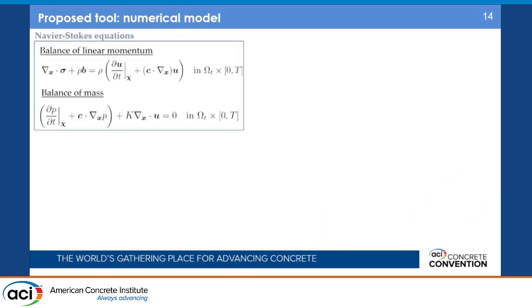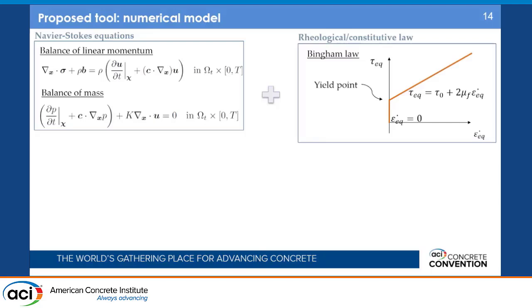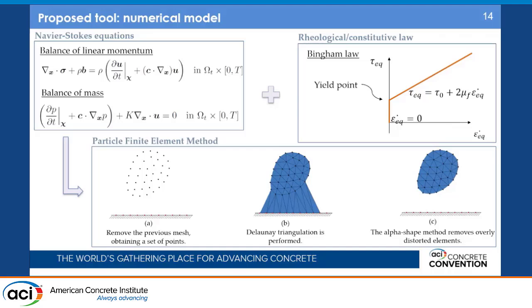So in a fluid model, the fresh concrete is treated with Navier-Stokes equations, which are coupled with the model for the material behaviors, and for concrete we can use, for example, the Bingham law. And you see that the yield stress, the yield point, is the main feature of this constitutive model. And then we have some finite element discretization of these equations that allow us to perform the simulations.